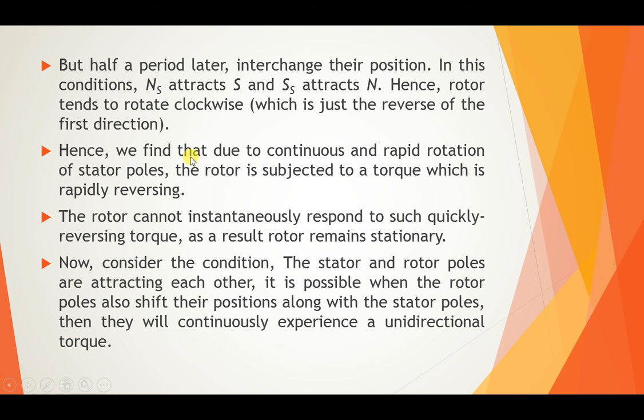Hence we find that due to the continuous and rapid rotation of the stator poles, the rotor is subjected to a torque which is rapidly reversing. The rotor cannot instantaneously respond to such a quickly reversing torque. As a result, the rotor remains stationary, and that's why a synchronous motor is not self-starting.